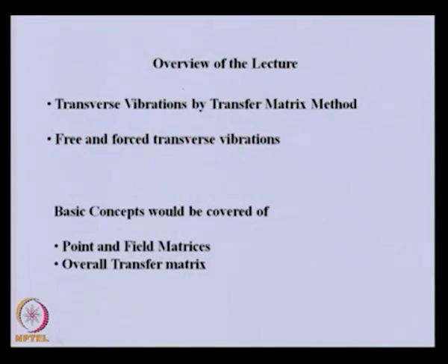Transverse vibration by the transfer matrix method. Free and forced vibration both we can analyze. Similar to the torsional vibration case, we will develop point and field matrices for transverse vibration, and have the overall transfer matrix concept, and then we can apply the boundary conditions of the problem to solve either free vibration or forced vibration.